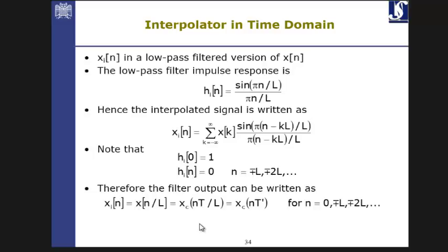That's the linear interpolation. But here it's not a linear interpolation. It's a sinc-based interpolation. We can investigate how it's different from the linear interpolator, but practically this type of interpolation gives more information to the signal and makes more sense than just using the linear interpolation.